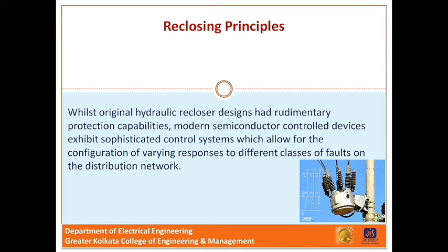If the recloser closes onto a fault, it is likely that the fault is a secondary class of fault, vegetation contact or equipment failure. An overcurrent fault would indicate a line-to-line class fault, which can be confirmed by negative phase sequence overcurrent protection, whereas an arc fault can indicate a line-to-ground or double line-to-ground fault.